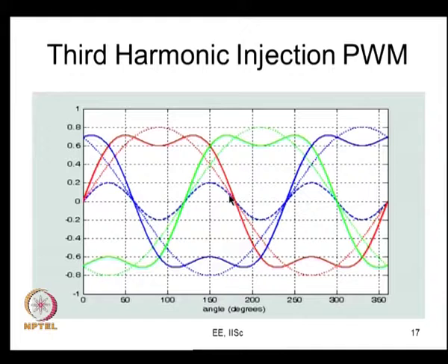Whereas switching loss largely depends upon the current. It depends on the DC bus voltage and the current, so its amplitude and the power factor of the current. Again, interestingly, for continuous PWM methods, it does not depend on the power factor also. It largely depends on the current. So, it is DC bus voltage and the current that are the main parameters here.